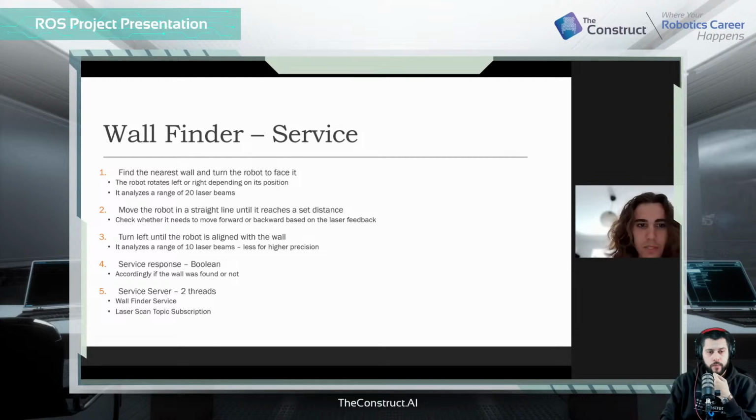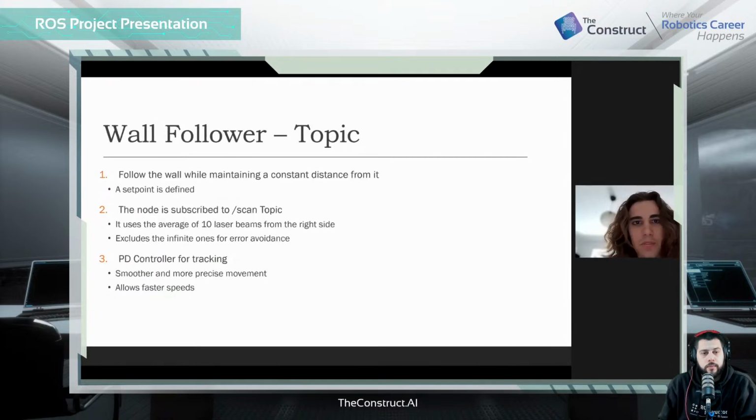The service response from the interface is a Boolean, and it says if the wall was found or not. Also, the service server has two threads, the wall finder service and the laser scan topic subscription. After that, the wall follower topic, I defined the set point. Like I said, I use the PD controller for tracking. This allows faster speed and smoother movement.